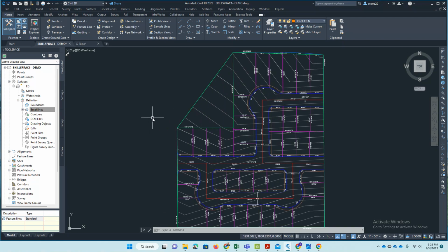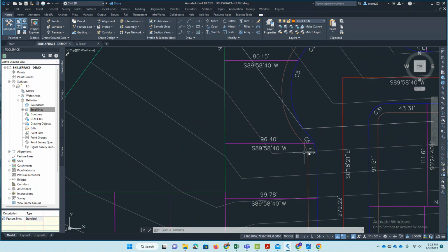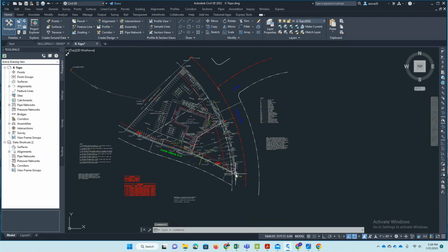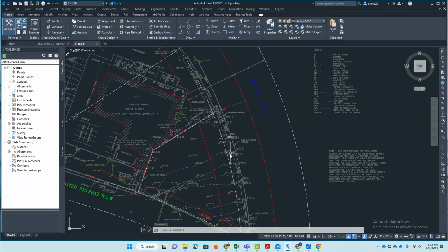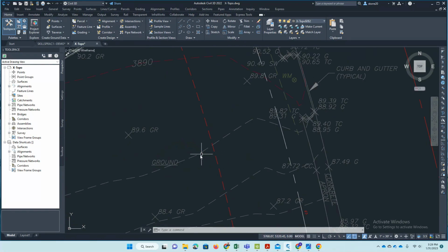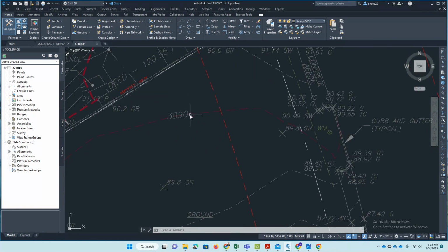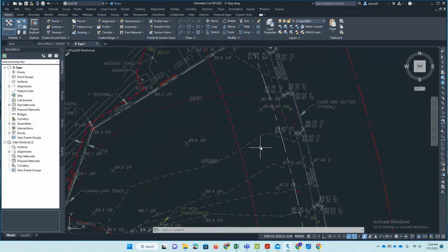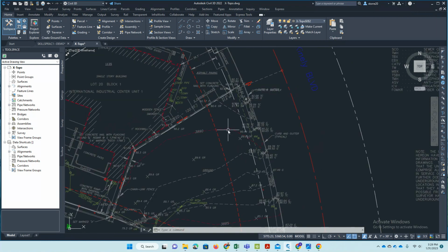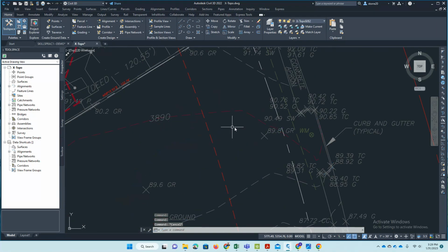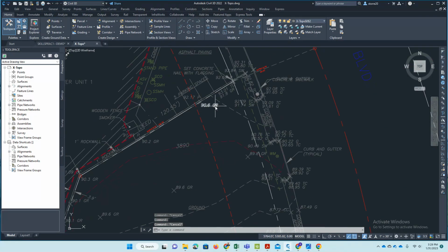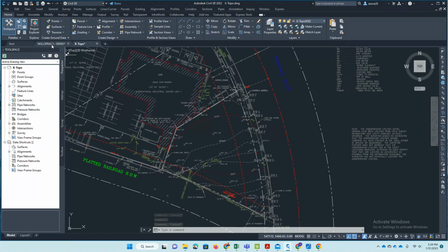The thing that I do want to do in this case is I want to make this look like existing ground. I have an example of a topo that's an industry standard topo that's done by a surveyor here in El Paso. And you notice existing ground is typically hidden lines. And the other thing too is depending on how much time we have, it might not be a bad idea to create a pen style to shade, because most of the time, whatever is existing, whether it's existing contours, existing curb, existing driveways and stuff, those are usually shaded. So it just depends on how much time we have.